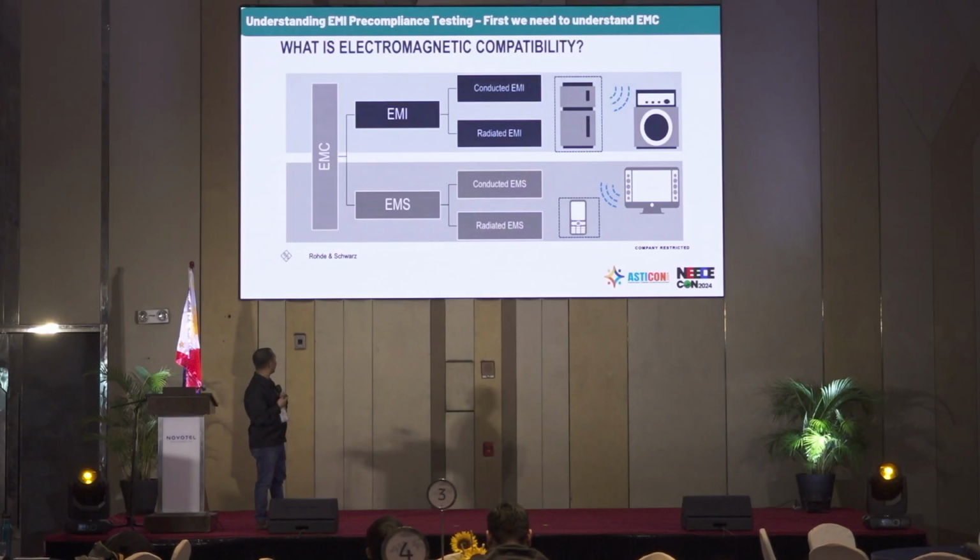We have EMI, wherein we need to measure the noise that our product is contributing to the environment. It has two parts. It can affect other products through conducted EMI, or it can also be affected by radiated EMI. So we need to test both EMI and EMS.